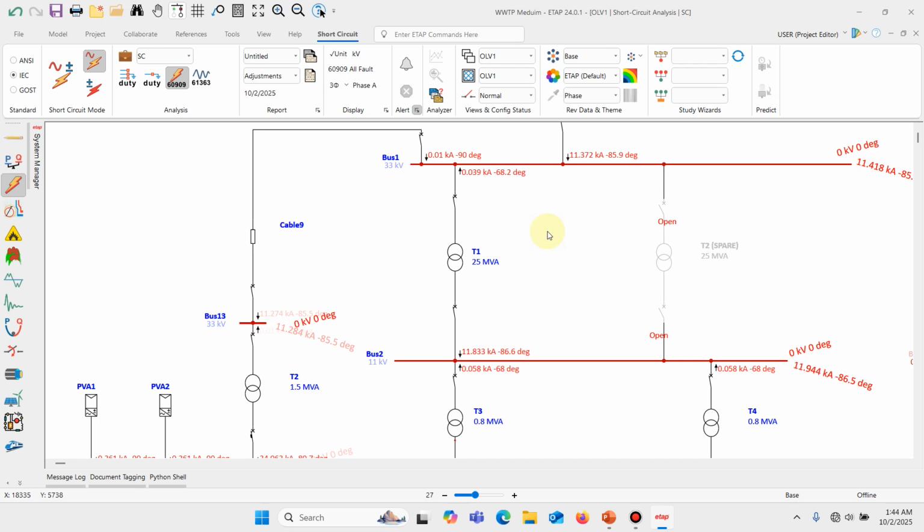However, the existing switchgear was rated 25 kiloamps. So during the first fault event, there was total failure. The downtime was 3 days. The repair cost was $20 million, all because someone said it's just an upgrade, no need for new studies. This is the cost of ignorance.